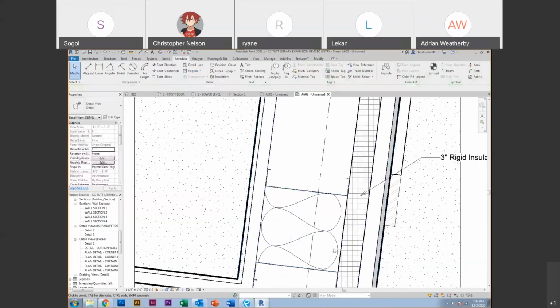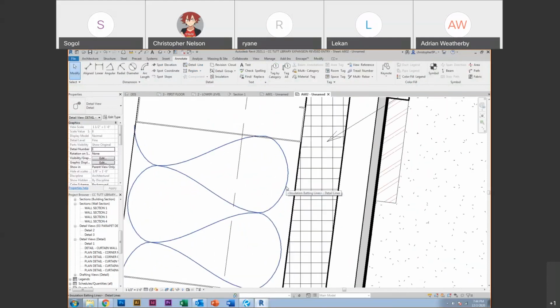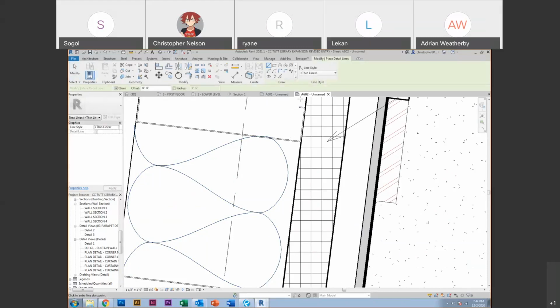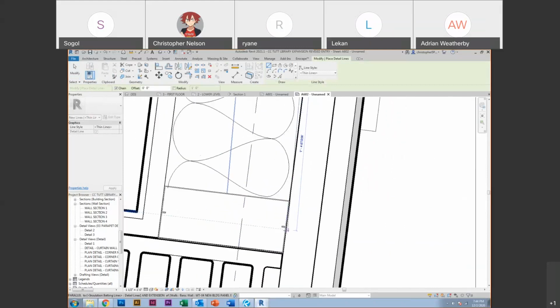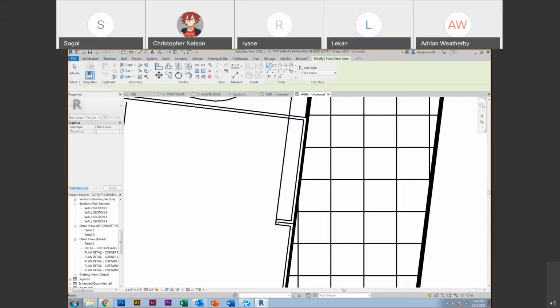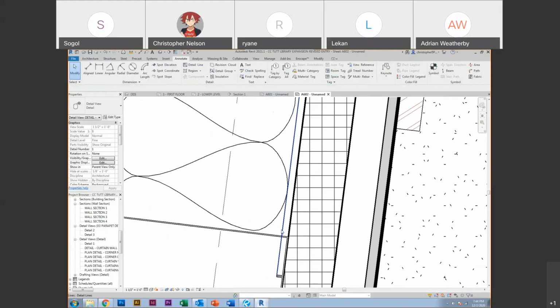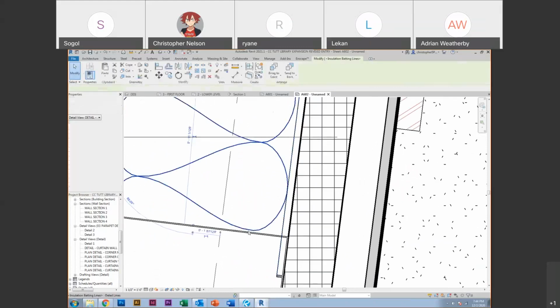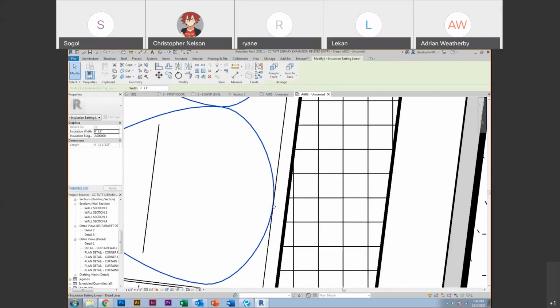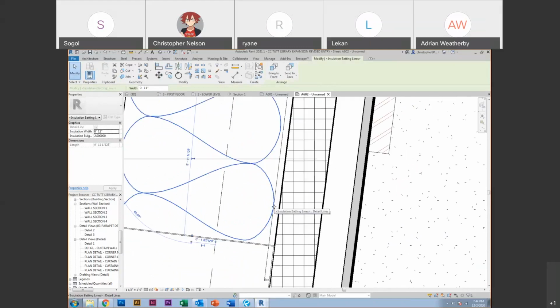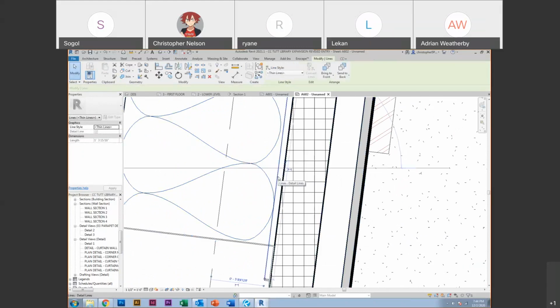And the reason why I do that is because if you draw the stud in section, like in elevation, if you're doing a section cut, you'll get these little dashed lines. So if I do DL, I usually get a dashed line following these little arms that turn in. And if you do a 1/2 inch off the insulation, it'll connect with it, but not intrude upon it. And it just reads cleaner to me. Like I said, people have different opinions on it.